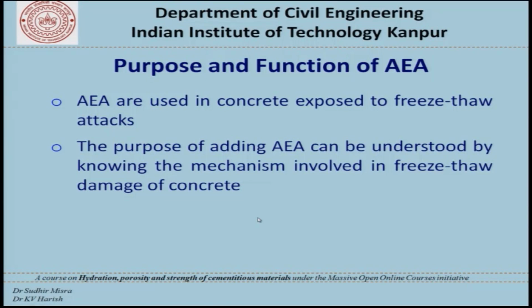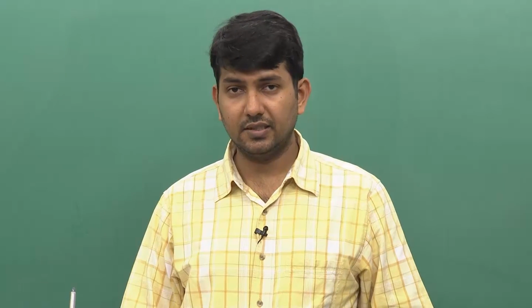The purpose and function of air entraining agent can be understood by knowing the mechanisms that are involved in freeze thaw damage, because the principal purpose of using air entraining agent is to offer resistance to concrete against freeze thaw damage.